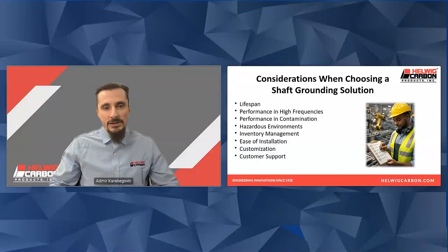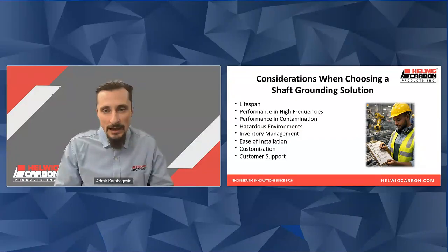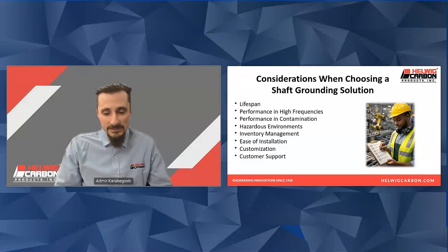So what are the considerations when choosing a shaft grounding device? Here are a couple of things that I look for. Lifespan: you could have something that works really well, but if it only works for a few months, is it really worth it? It's got to perform in high frequencies. It's got to perform well in contamination and hazardous environments. It's got to be easy for inventory management, ease of installation, customization, and the company should be able to provide customer support.